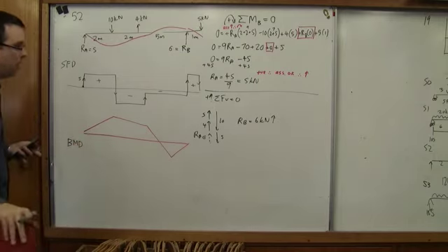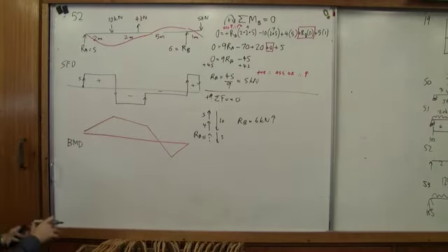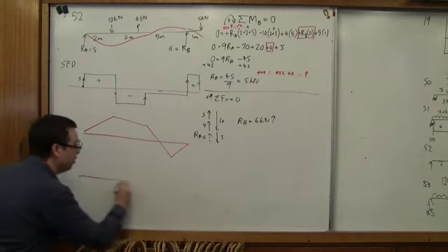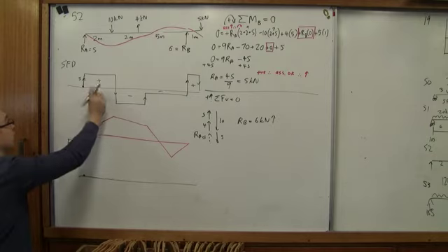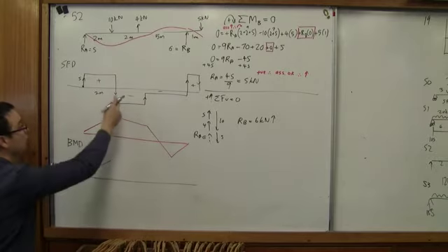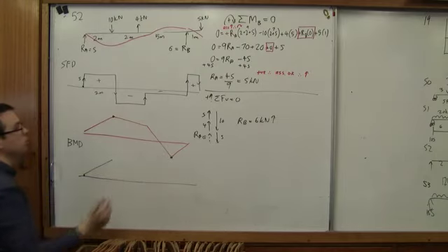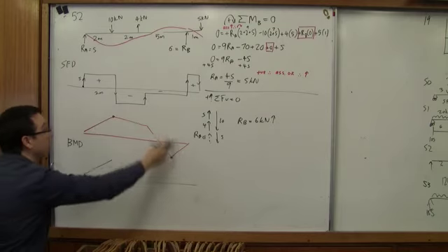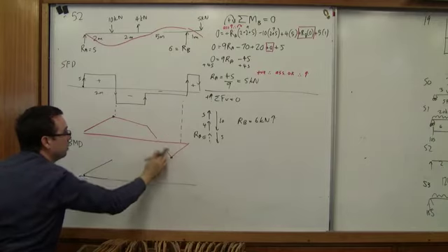Okay. I'm going to sit just so I can access more board. Okay, so once upon a time, there was a bending moment diagram that had 0. The first block had an area of 10, right? 5 times 2 equals 10. And so that's going to be this value here, 10. We predict that our maximum values are going to be here and here. When we talk about maximum, remember we talk about absolute values? We have maximums and minimums, but our positions do line up. So I should draw that a little bit better.